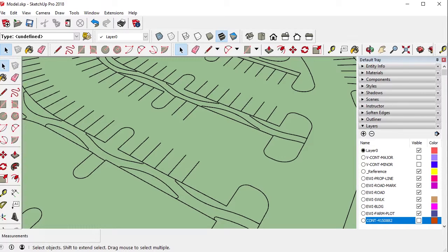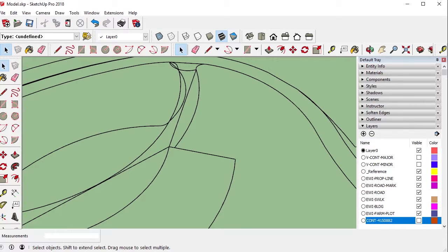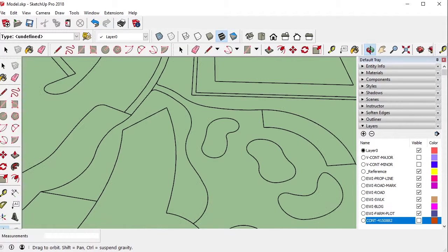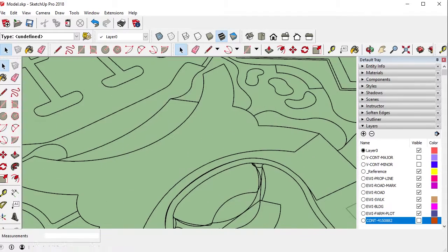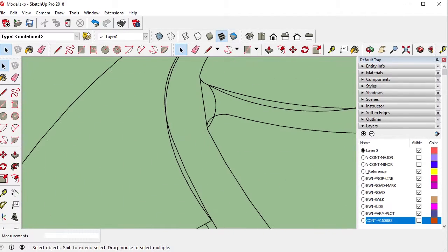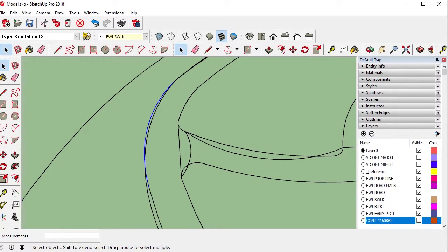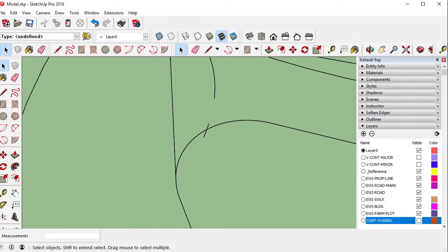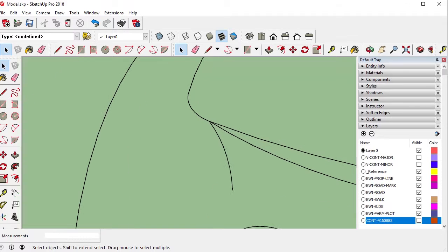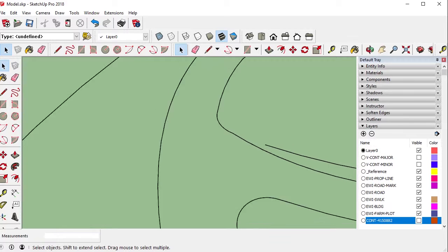I'm going to go ahead and pause this and let this happen. I'll come back. As I'm working through this, I'm also noticing other line work that needs to be cleaned up. You don't want to have double lines, for example, running through here. This may be a step you have to do in CAD before this step, but we want clean lines that represent all of our surfaces. This would be very confusing for SketchUp to handle. So if this is all the same surface, go ahead and make those clean. You can do this in CAD before bringing it into SketchUp, so it's actually cleaner.